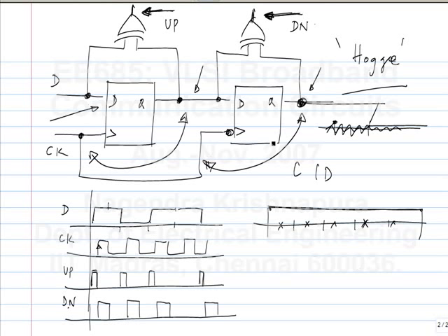See, in a clock and data recovery circuit, when you start up, you can't say what it is, right? The clock frequency can be different from the data also. In the first flip flop you are sampling at the positive edge. And the data must come to the input of the second flip flop before the next edge of the clock. Oh, you mean the clock to Q delay must be less than half a period? Less than half the period. Yeah, that will be there, right? Otherwise, you could probably not design the flip flop very well. So that is a very huge error.